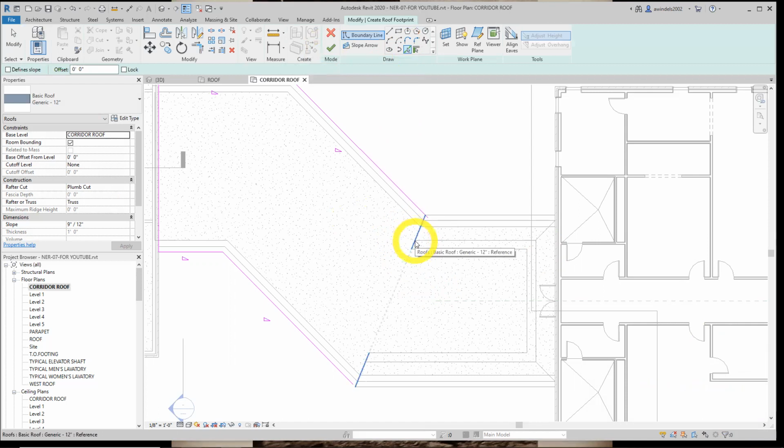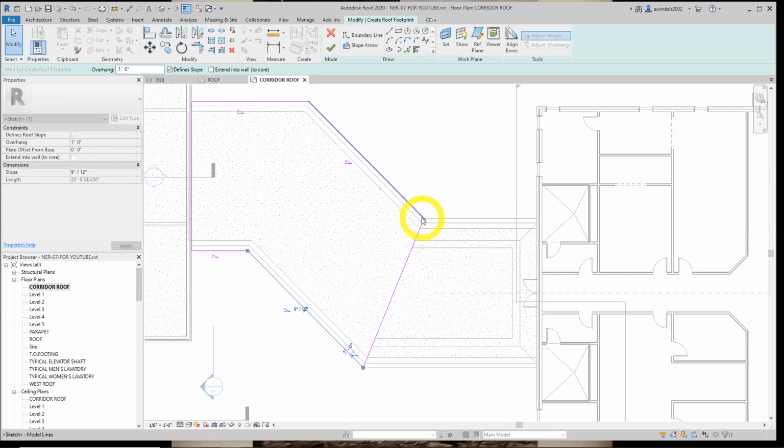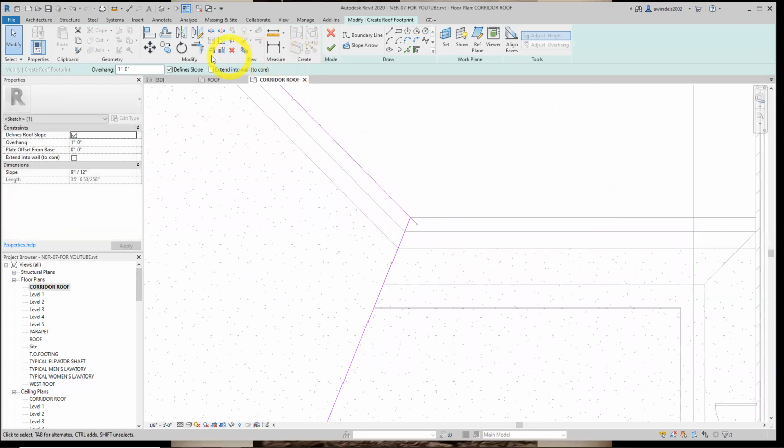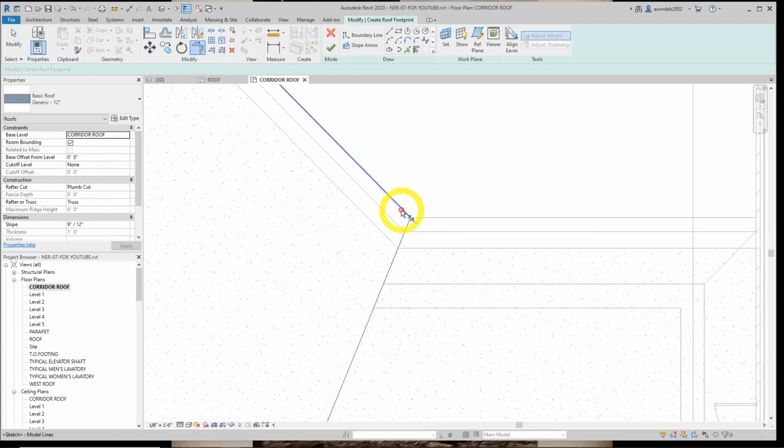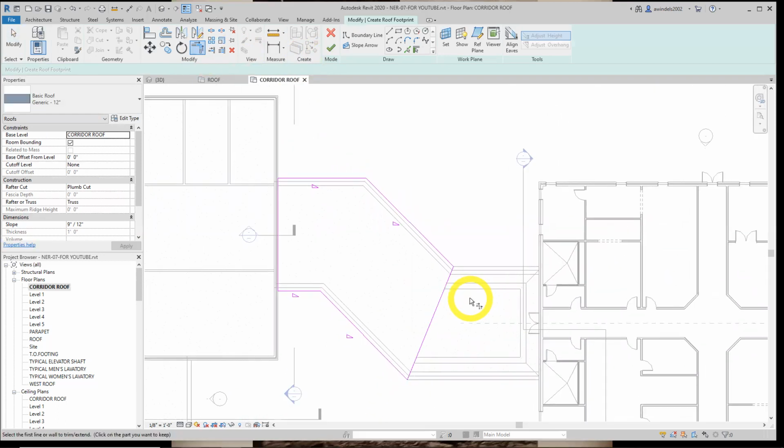We'll use pick line for this one too. This will help finish this off. This is our 6th line. We did the same on this side, this gable end, and then this line. We're going to make sure this is off, no offset, and pick line. It grabs the whole line. Got a little escape. We'll clean up, trim to do here. And there we go.